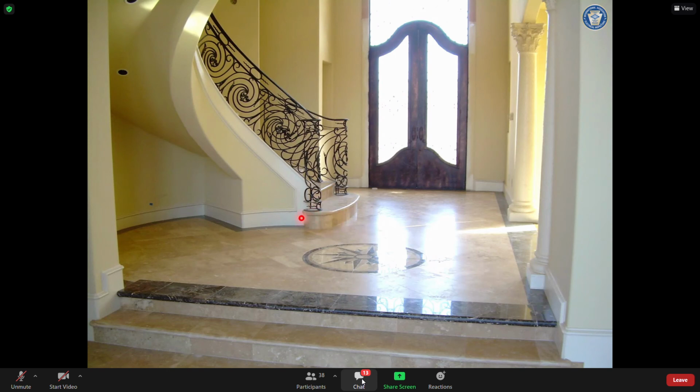So look right here. Whoop. Is that 3 feet or wider? Yes. So I'm gonna need a receptacle right here. That right there was about 3 foot 8 inches from right there to the end of that column right there. So a receptacle would be required right here. That right there measured about 4 feet right there. So a receptacle would be required right here. And this right over here measured about 3.5 feet. So to make this code compliant, you would need 4 receptacles in this particular foyer right here.